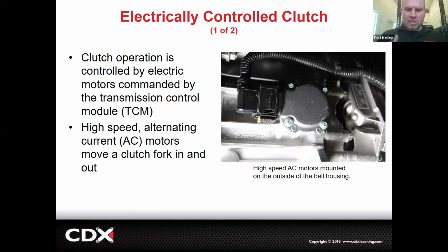So this is kind of where I'm going. The way the dual clutch transmission works, it is like a manual. It truly is. It's not planetary gear sets and clutch packs. It's literally gears on gears and a clutch that's going to be actuated, in the GTR's case hydraulically, or in this case, literally mechanically. So the way we work on it is actually much more like a manual. And that's why dual clutch is part of the manual curriculum.